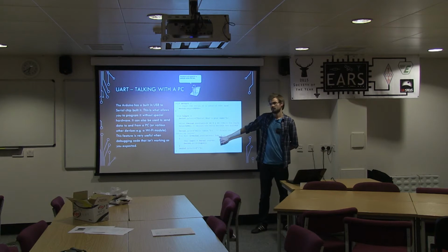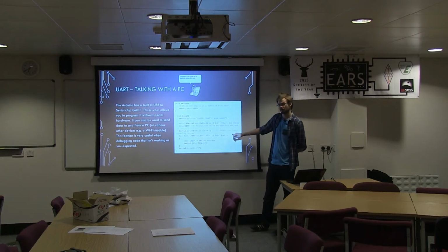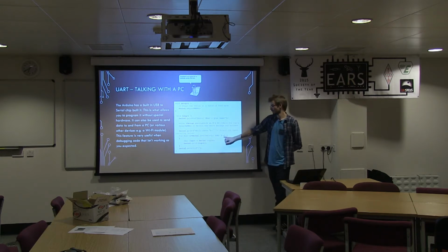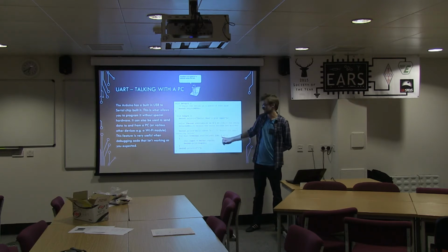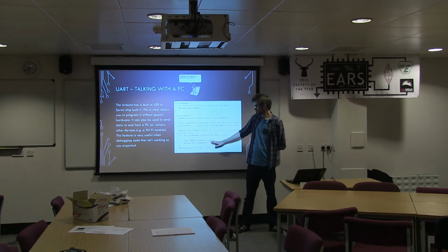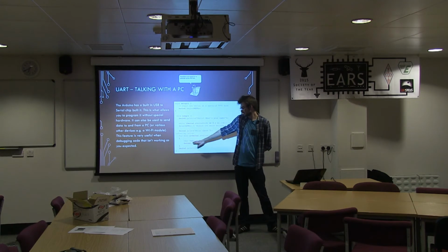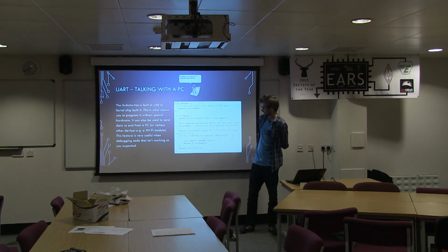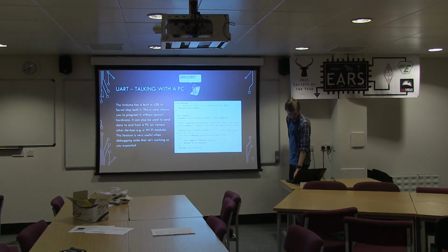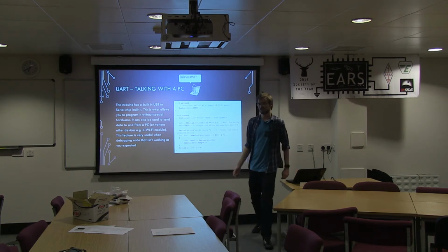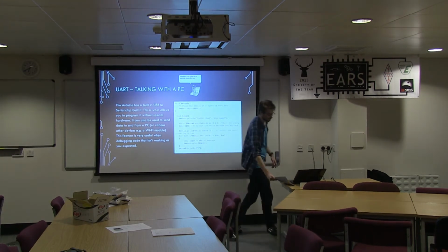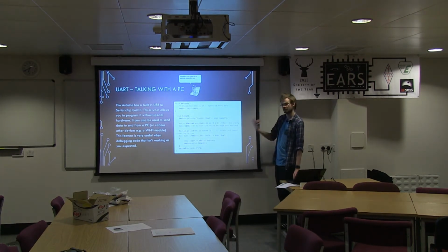This now reads in. This is just the standard loop that you should have seen before in the other lectures, but this one is counting down, which is the difference. It starts at how many characters are available and counts down until it's read them all. It's doing a very simple thing: storing the value read from the serial port using Serial.read into a character and printing it out. Then it prints a new line at the end so it can loop around without piling everything on one row. You should have some code for something like this, so you can try it out in a bit. We'll test it out and you can get it actually working, sending stuff backwards and forwards.